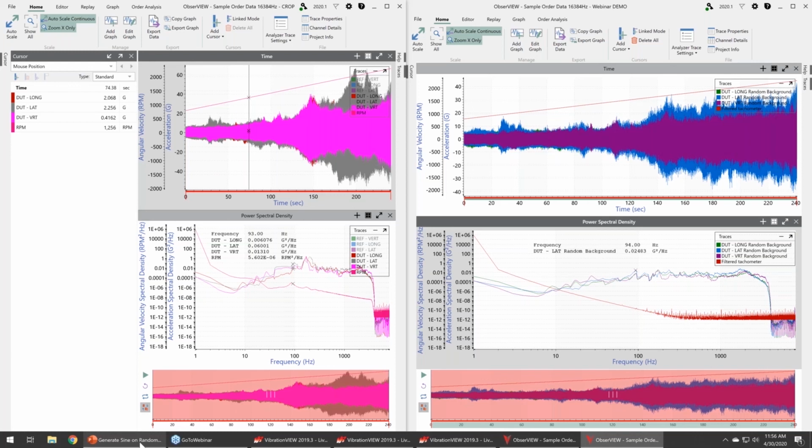Another direction that I'm looking to go in future development is to actually start doing cycle counting and have a way to display and view that so I can look at my real world data, accelerate it, calculate the appropriate cycle counts, and then compare that to the cycle counts from the shaker test. That would be a method.